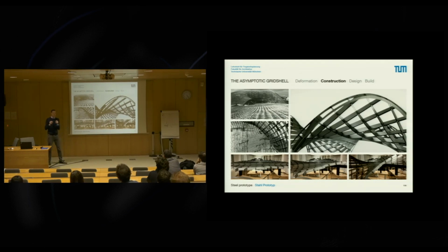Why I'm saying it like that is that when we first did it, it was quite a surprise. It's enough that you just push down one corner and the whole structure will follow this mechanism and go into the correct shape. That means you don't need any form scaffolding. You can just push it until it's 90 degrees, fix the nodes, and you will have the correct shape.